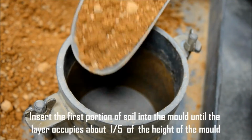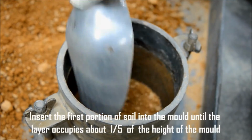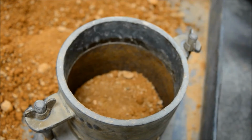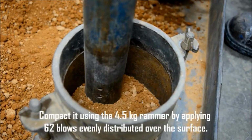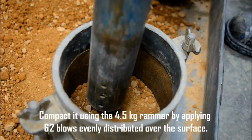Insert the first portion of soil into the mold, until the layer occupies about 1/5 of the height of the mold. Compact it using the 4.5 kg rammer, by applying 62 blows, evenly distributed over the surface.